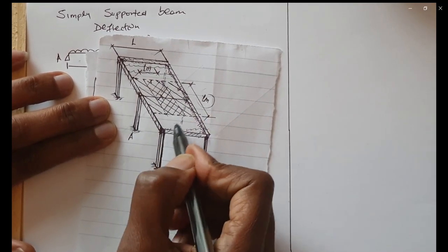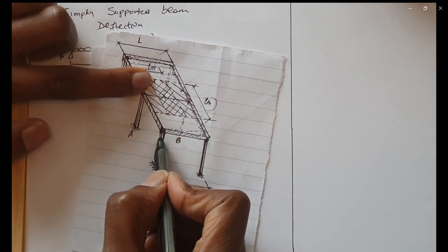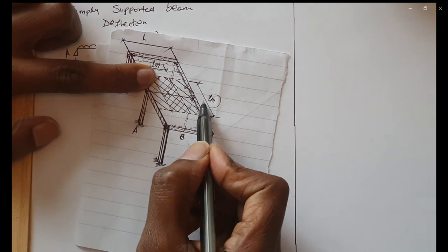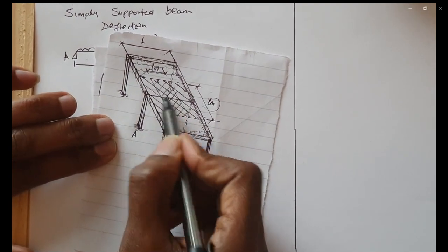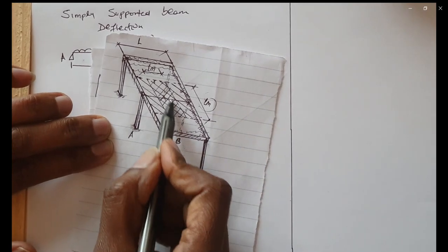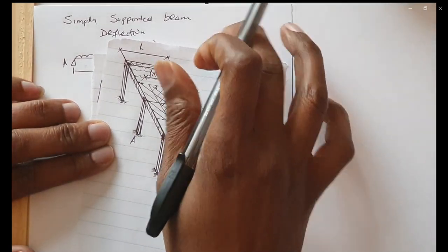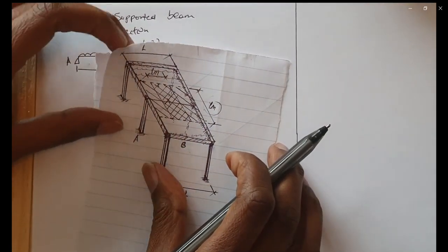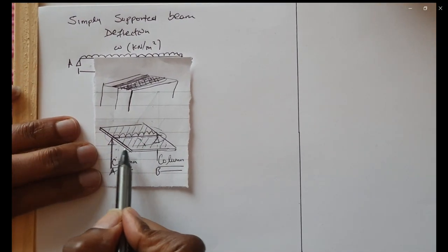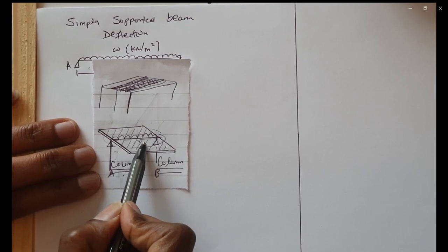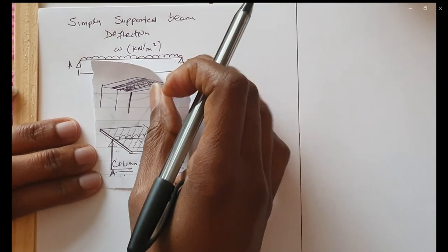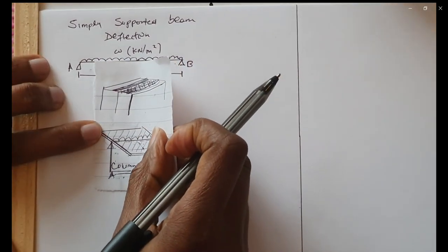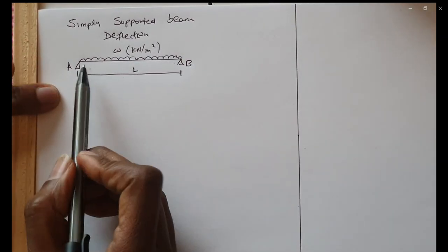If the lengths between the two beams are longer, then we have to take half of it, and then take one strip of 1 meter and work out the dead and live load. And then using Eurocode or British code, we can calculate the total load to use for calculating the bending moment. That is the simplest way of representing it.